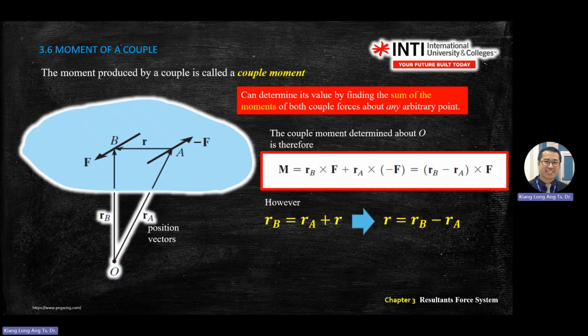So basically you just take F multiplied by R, or cross product, the perpendicular distance between the two forces. You still get moment in the couple setting. So the moment in a couple is equal to R cross F. We're still applying M equals R cross F. It's just that we're moving the force around.